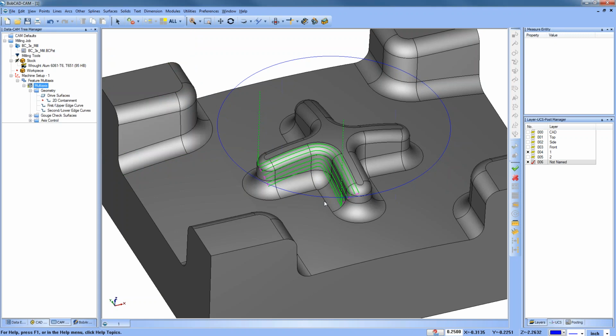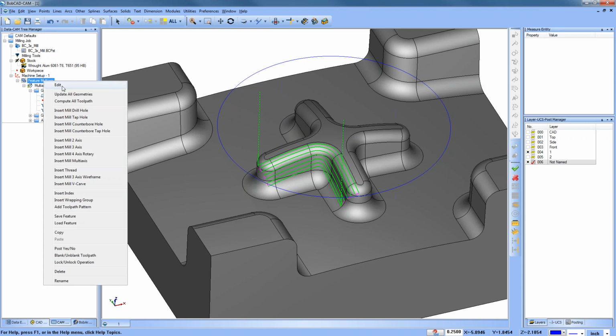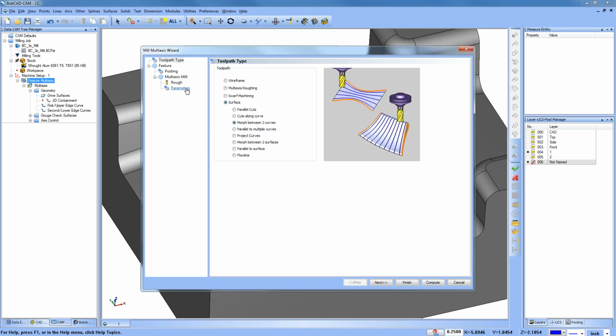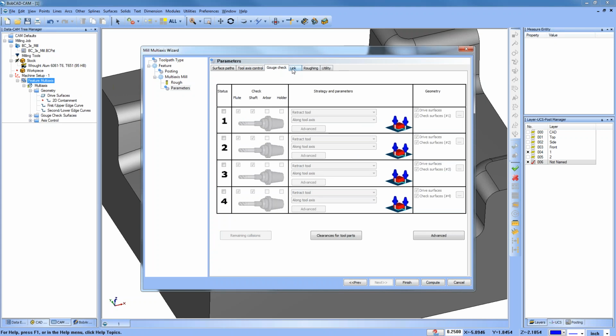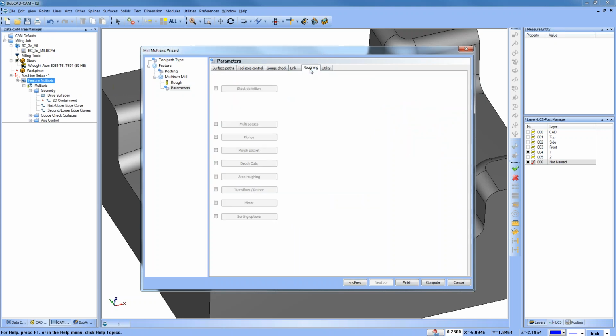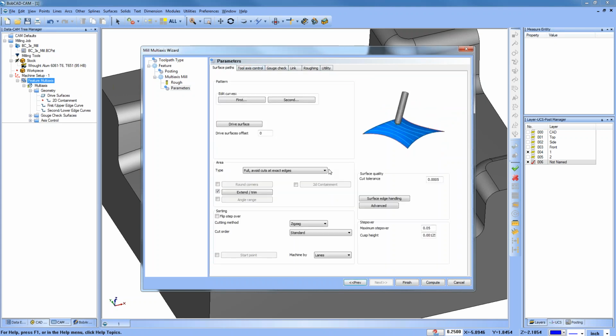Now, what I've personally found is that the surface-based toolpaths are more surgical. You can really go in and target areas of your model that you need to clean up, blended surfaces, compound curves, etc. When you start editing your settings in this feature here, there are a lot of settings. I've definitely spent some time with these dialogs, so I have a decent familiarity with them.